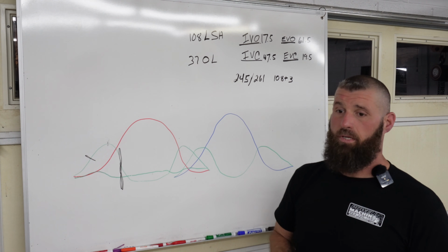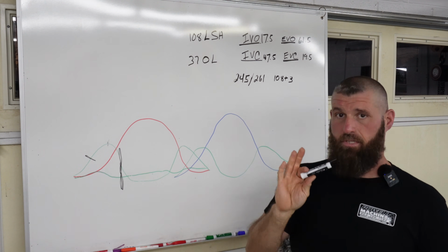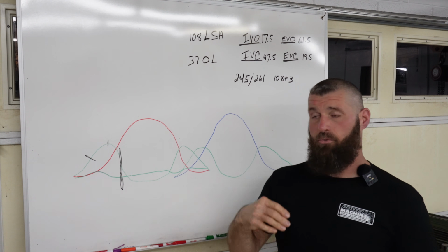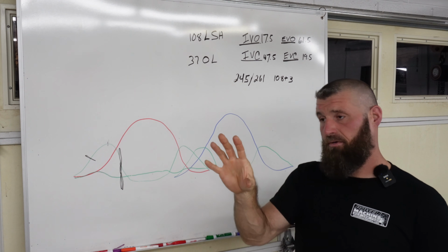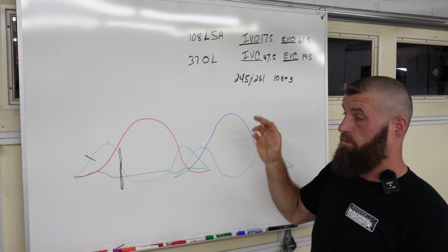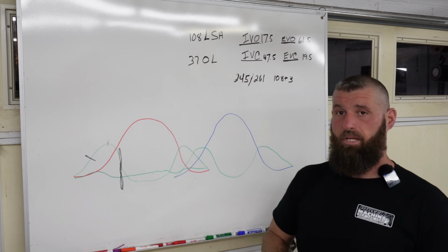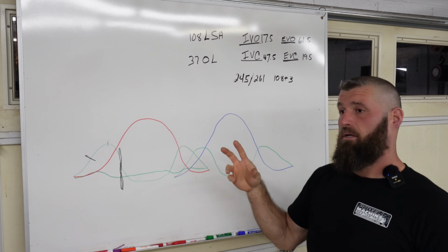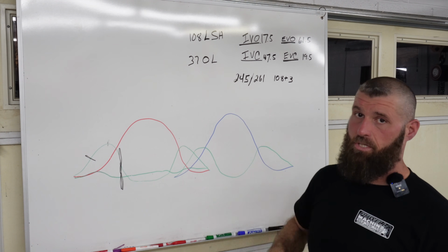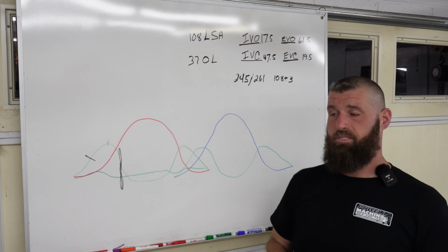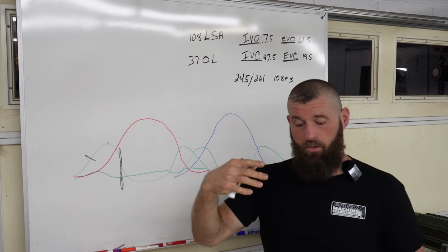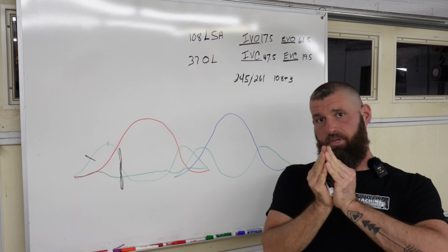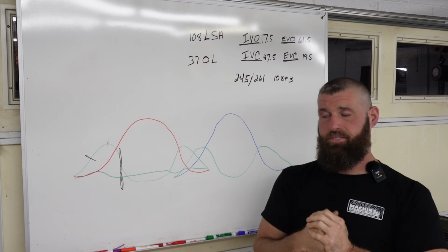And so the exhaust has just a little less lift, 5 thousandths, than the intake at the lobe. And generally speaking, when you spread the duration out at the same lift, it brings the acceleration down. Now we can tweak that some, but generally speaking, we slow the exhaust lobe down because of expanding exhaust gases. As you know, the piston is coming down, like we're on the power stroke. The gases are expanding, pushing the piston down.